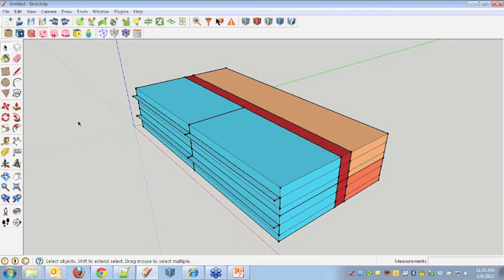And one thing to note too is that this data, like for example, occupancy schedules, is being applied to this OpenStudio model. But then if we choose to do an energy simulation, that's automatically passed through to the energy simulation tool, EnergyPlus. Likewise, it's also automatically passed through to Radiance. So when you're doing a daylighting analysis, it derives its occupancy schedule directly from the OpenStudio model. So the assumptions that those things are based on are synchronized across all of the models, the energy model, the daylight model, et cetera.